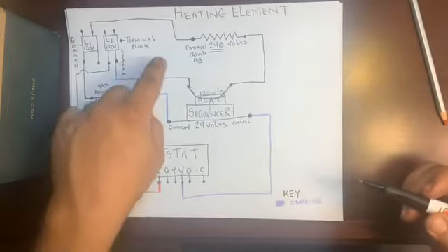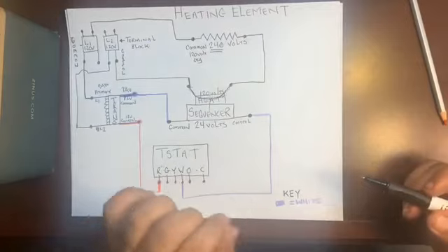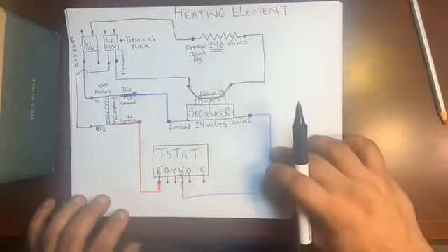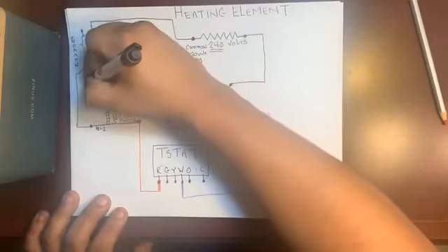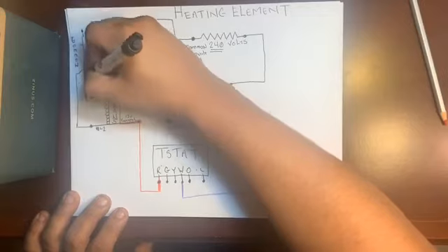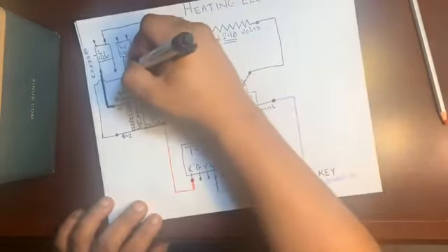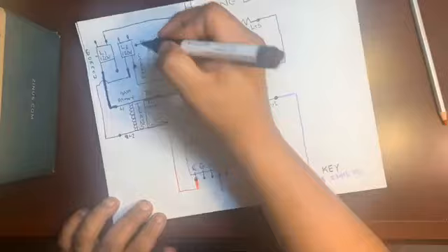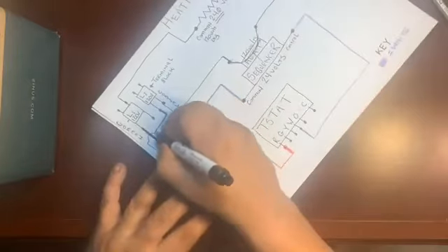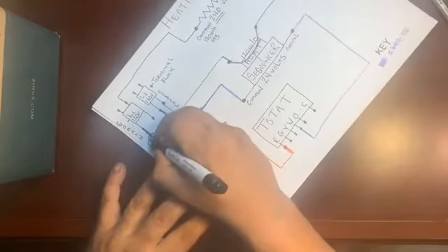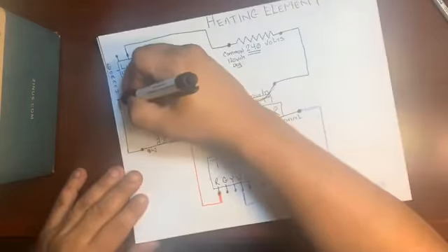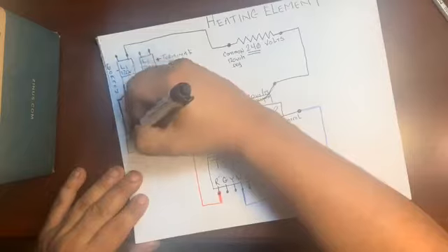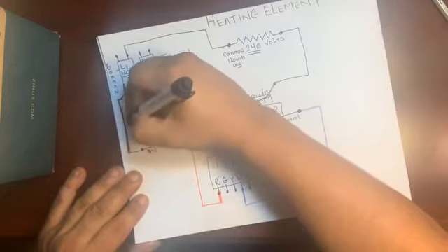You see how these wires are just about the same distance, the same thickness. Color pencil's a little thicker. But on a real diagram, what you're going to see is that high voltage is extremely thick. Very thick wires. This is done on purpose because just by glancing at the actual diagram, you can designate the thin wires from the thick wires, and you can see that, hey, this is a low voltage wire because it is so thin compared to these much thicker wires.